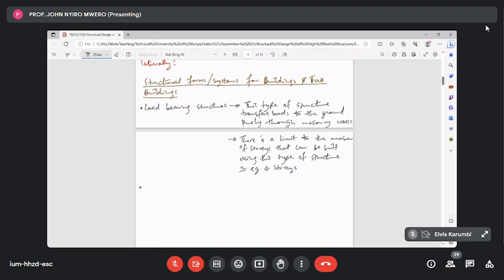So eventually he changed. But if he was to do this, and for example we were to get a tremor, there was a danger that the building would just crumble like a deck of cards. Okay, so if you have to build taller than what you are allowed for load-bearing masonry walls, then you could consider what we call a frame structure.